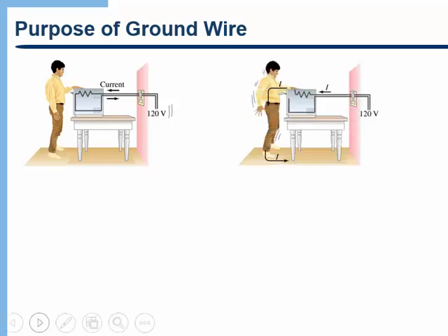But then one day, from tapping it every day for many days, all of a sudden one of the wires comes loose in that microwave. And it turns out, unfortunately, it's the hot wire, and that wire makes contact with the inside of the metal case. Well, you'll notice that now the electricity is going to flow through the metal case, through you, and back to ground this way. Because remember, the neutral wire is literally connected to the ground.